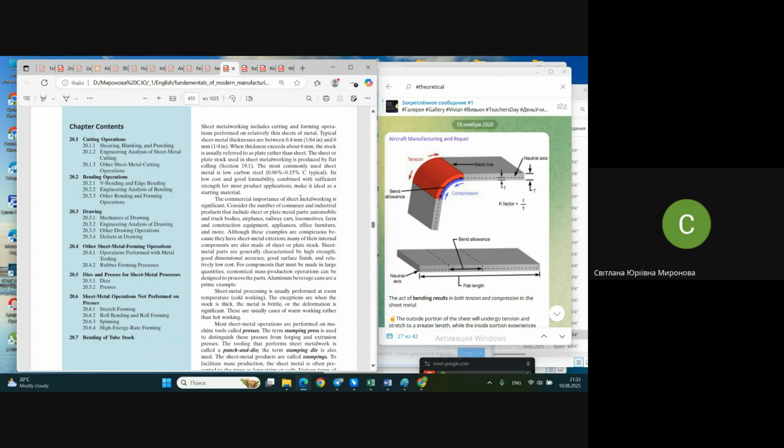And one more unpleasant moment when we're working with sheet metal is that during deformation of the sheet metal, in some cases we deal with a spring back effect. In some cases, the spring back effect is practically absent, just because the part passes through extremely severe plastic deformation. It's already forget about any elastic energy. In comparison to this plastic deformation, the spring back effect is practically absent. More probably we tear off the part, but certainly it's not springing back.